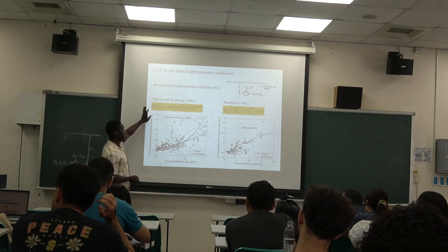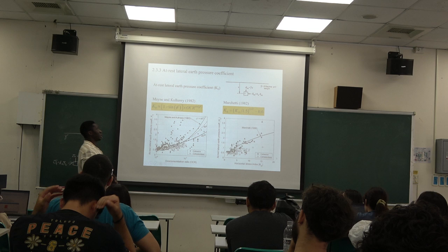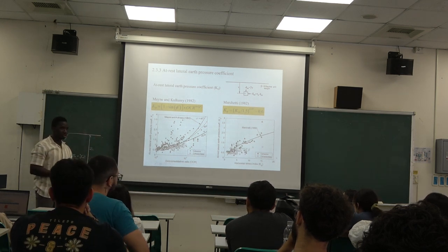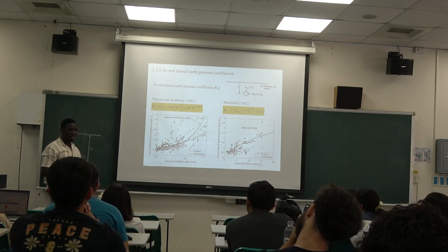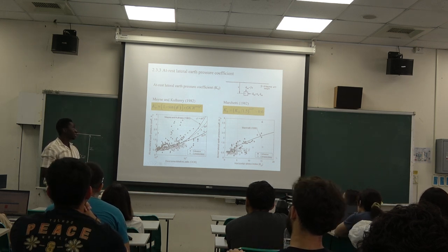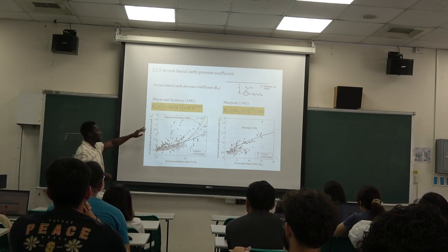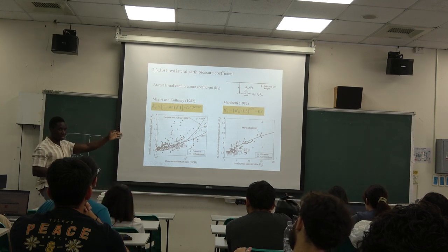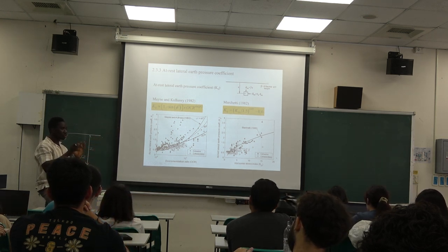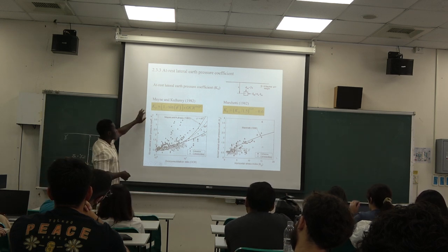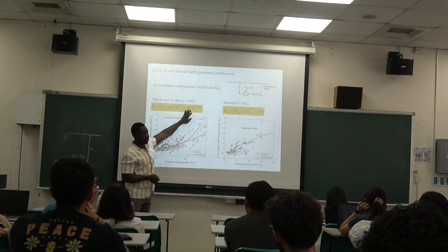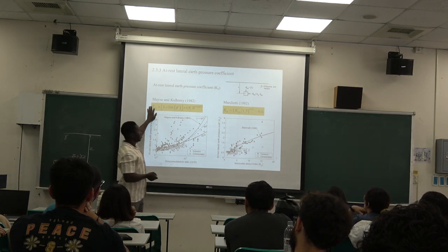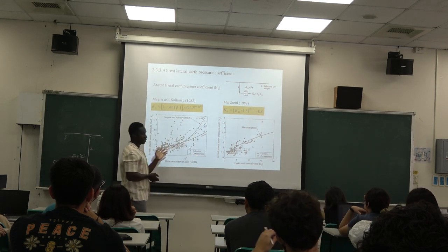So here we have some equations that can be used to determine the K0 value. This K0 is dependent on what? The friction angle. So you can see the friction angle is a very, very important parameter. You can imagine how bad your design will be if you get the wrong friction angle value, because almost everything you are doing relates to it, especially when you are dealing with sandy or coarse-grained soils. So this is our K0, and this time we will include the OCR. It also depends on the OCR ratio. So you have two different equations, either this or this, and all of these are okay. It depends on which one you want to use.